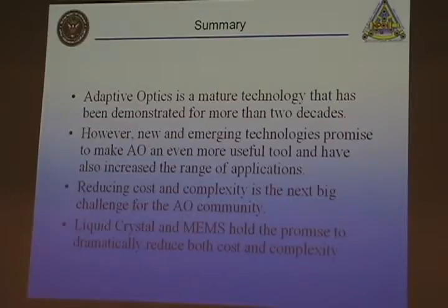And then if this is an optically addressed device like the Hamamatsu PAL device, which uses an optically sensitive material here, which changes these light intensity variations into a voltage. And then you have a liquid crystal layer in here, which will change its index of refraction depending on what that voltage difference is. And you bring a beam down here, it's gone through that same sampled atmosphere. When you come off the liquid crystal now, this aberration has been corrected.